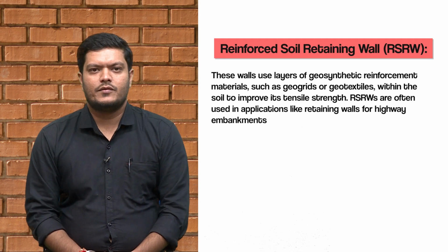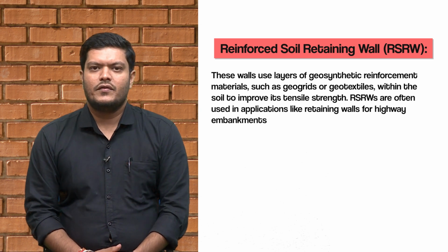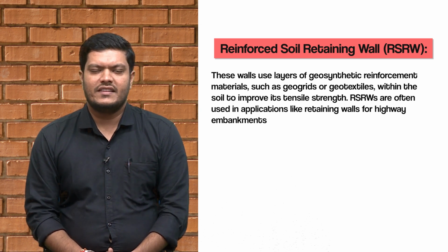Second, reinforced soil retaining wall, RSRW. These walls use layers of geosynthetic reinforcement materials such as geogrids or geotextiles within the soil to improve its tensile strength. RSRW are often used in applications like retaining walls or highway embankments.